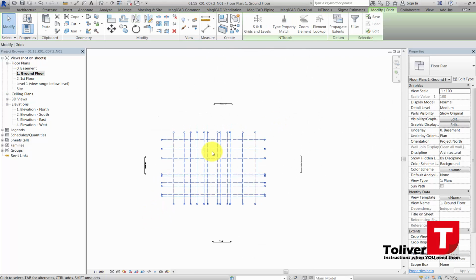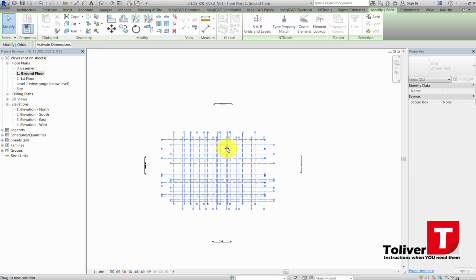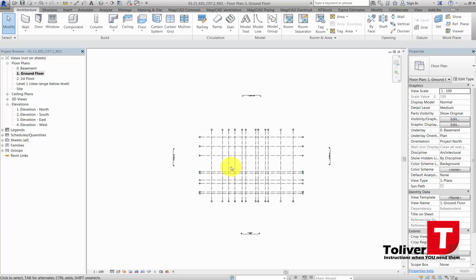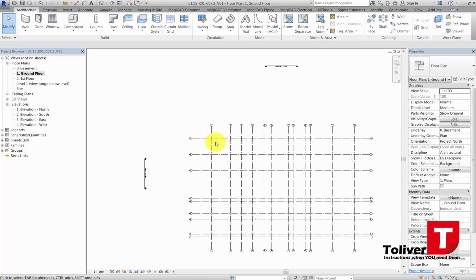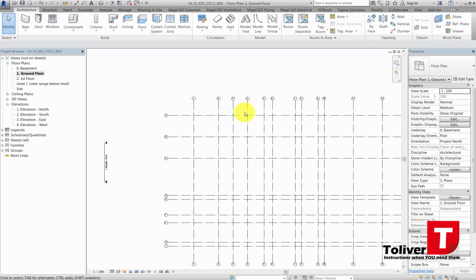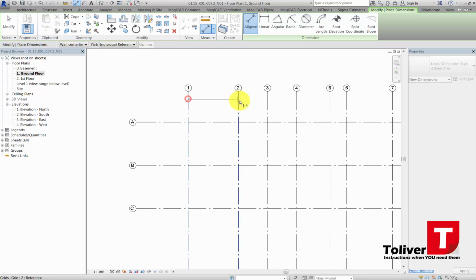What I usually do then, I just mark it all and drag it by holding down the left mouse button while I press down, and then move it. And then it looks kind of center, or okay in my opinion. The next thing I want to do is put in the dimension labels, so I know the distances are actually correct. So I'm going to go up to Annotate. Under Annotate, I'm going to choose Aligned, and I'm going to be just clicking on them as I go.